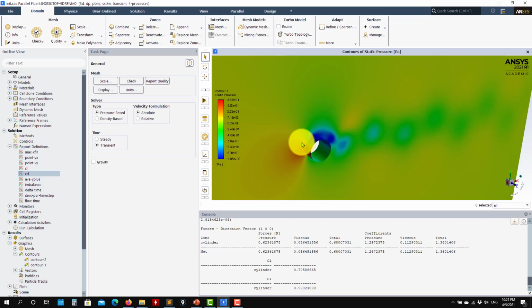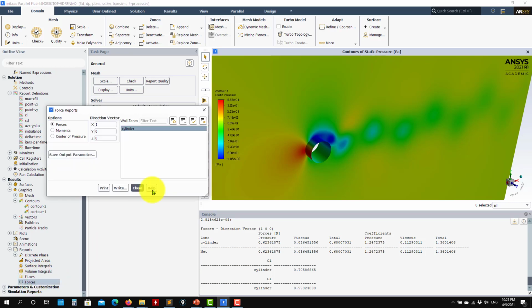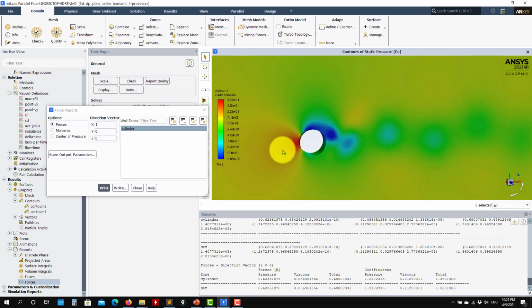Probably later we do airfoils and we'll see that better. But for instance, if we go back to the cylinder case, and this is my mistake, I didn't show you this. Let me show you here. You have in results, this is the 3D case, and then I will show you something in the 2D case. See here that you have forces, and you can compute them here, print, these are the forces in that reference axis.